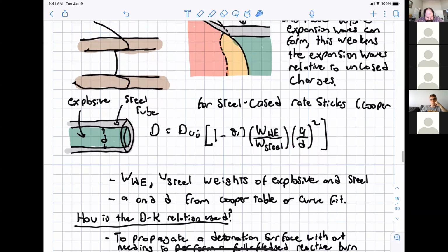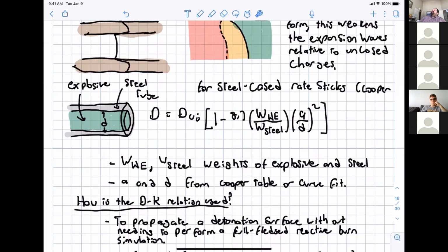Okay, and that means for those of you that actually work with propellants, when you open up the crates, you need to use anti-sparking tools, for obvious reasons. And anti-sparking tools are made of beryllium often. So you need to be very careful that you don't produce any sparks or small chips of your tools when you do that. Usually we make them out of beryllium copper, and beryllium copper is not toxic to handle, or even machine.